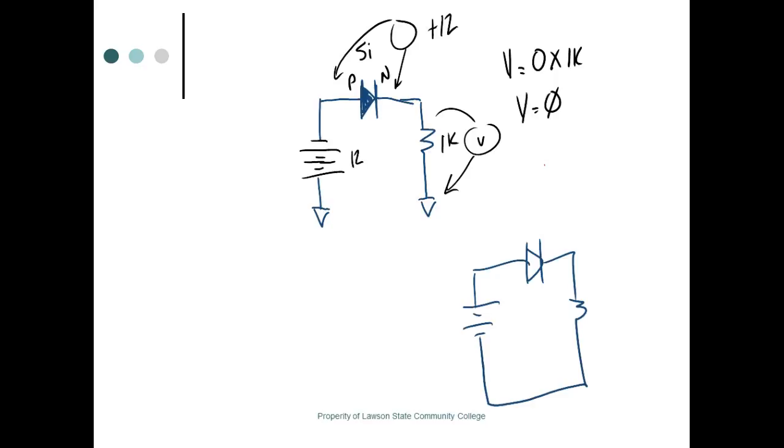And people will do that. They'll go over there and say, well, let's see if there's power on the switch. And they measure across the switch, and it measures 0. Oh, there's no power on this switch. And they stick their hand in there, and they're working in industry, and everything's metal, and everything's grounded. It might not hurt you much here because in residential, we use mostly plastic boxes. But in commercial and industrial, we use metal boxes, and those metal boxes are grounded.